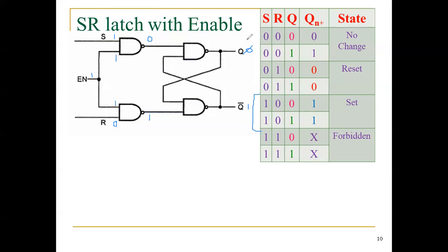Please listen carefully, this is a very important thing. Opposite to the previous state. So 0 is given as input of this N3, that makes the output equal to 1 here. That 1 comes to here. All the inputs are 1 now, hence it changes this into 0. Then for the same input condition, I made the assumption like this. Instead of 0, now I assume this is a 1.